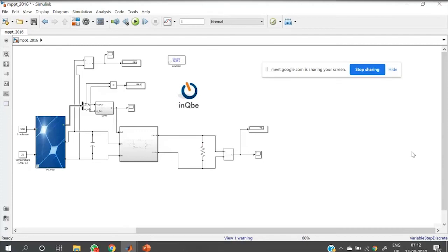We should have a proper algorithm, just like the hysteresis current control algorithm. It will maintain the current irrespective of fluctuation in the grid. That is based on the control algorithm, not dependent on the MPPT side. It is purely dependent on the inverter and control part.